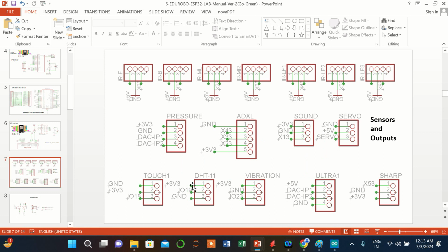This will simplify, and as I mentioned, no need of having a sensor also, because on the board we have provided a DHT11 connector, where one side you have VCC, other side you have ground. So you just short circuit pin number 2 and 1 if you want to give high voltage, or if you want to give 0 volts, short circuit pin IO19 to ground. We cannot do this with other pins because the center pin is input, and the left hand side and right hand side are VCC and ground.